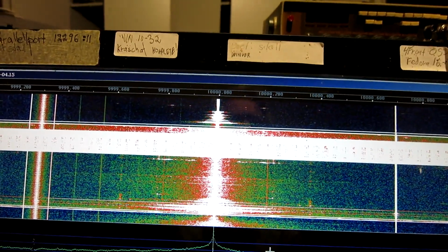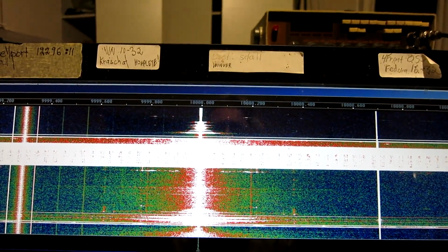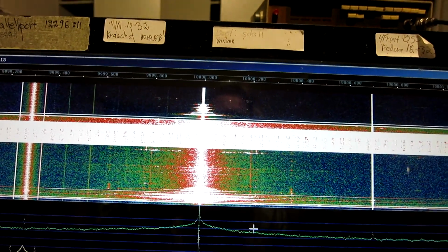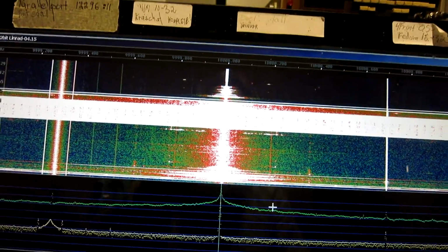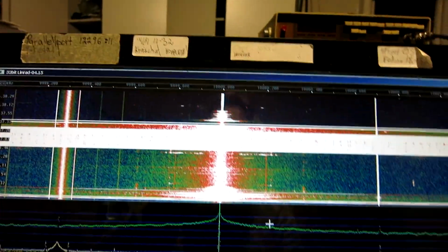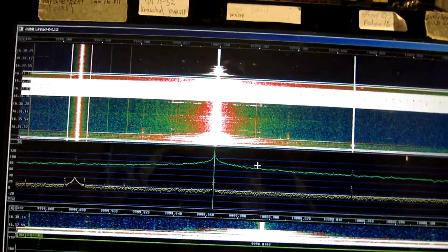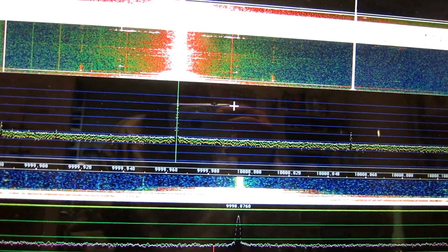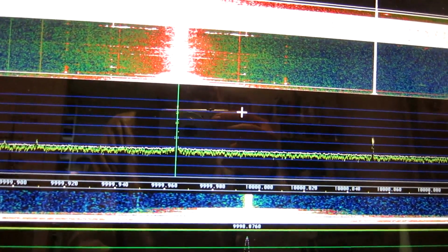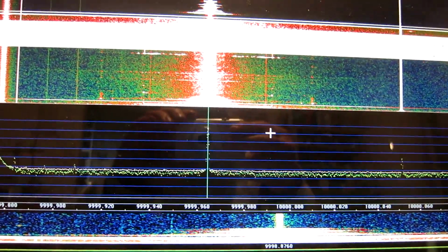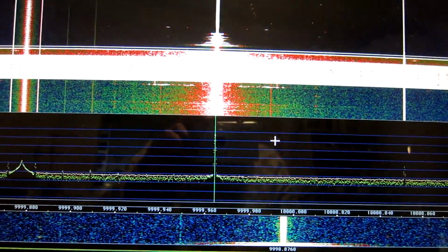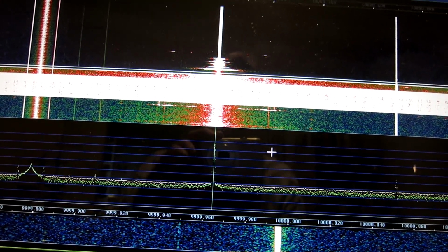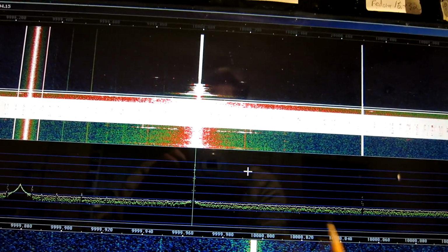Here is number 163, the best one, at minus 24 dB, meaning 24 dB attenuation. And I haven't changed the color scale on the waterfall. And I can look for the effect of correlation spectra by clearing it. And I have to wait some time until I see something. And only at very close range I see noise from the crystal. Otherwise it's the flat noise floor.